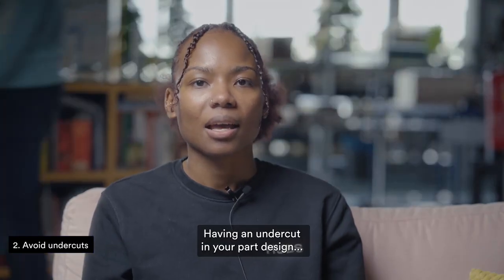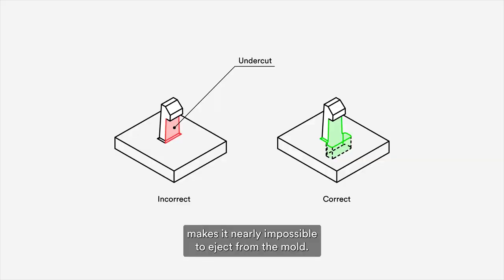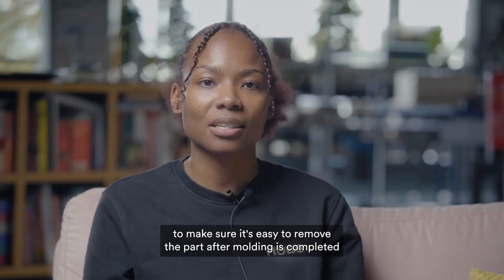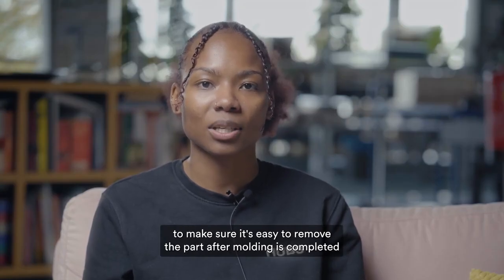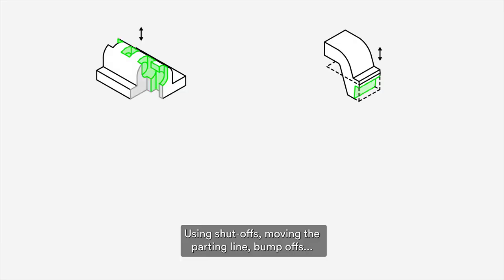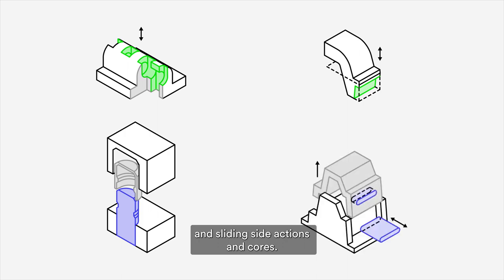Avoiding undercuts. Having an undercut in your part design makes it nearly impossible to eject from the mold. We recommend these 4 ways of avoiding undercuts to make sure it's easy to remove the part after molding is completed. Using shut-offs, moving the parting line, bump-offs, and sliding side actions and cores.